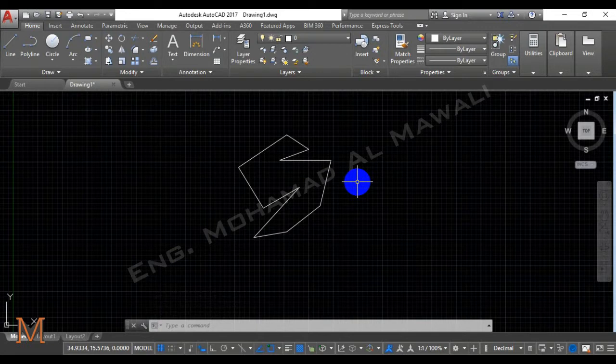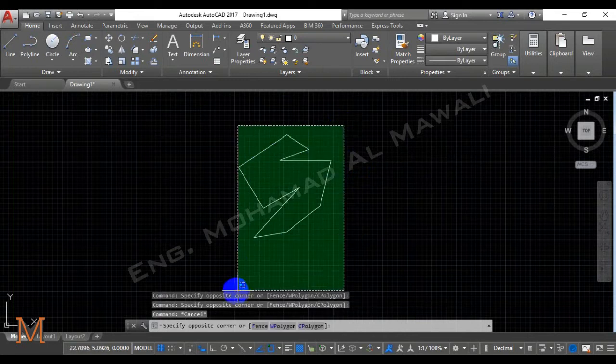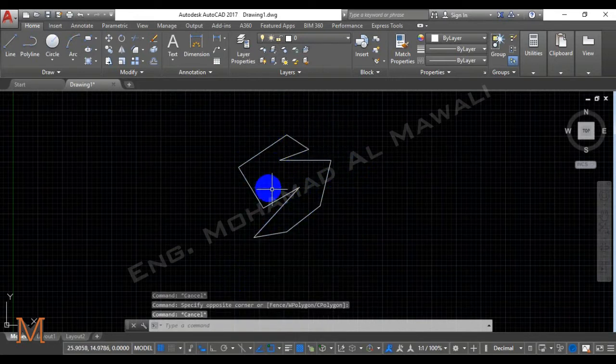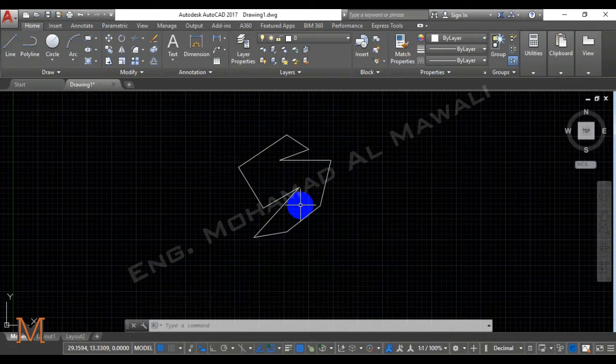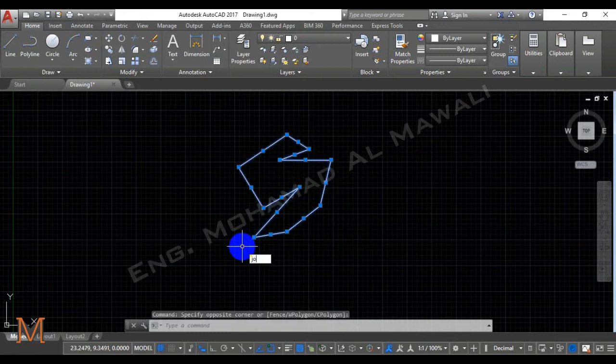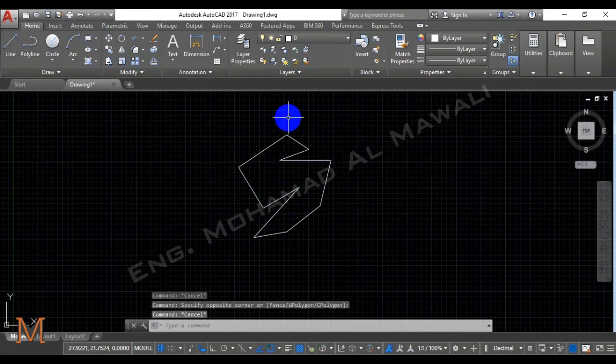So to be solid in 3D models of AutoCAD, those lines need to be continuous, or they need to be for one material, because if you extrude a 3D model of those lines, you will not have a solid material at the end, but you'll have an open one. So I need to apply the join for those lines so they can be one shape.